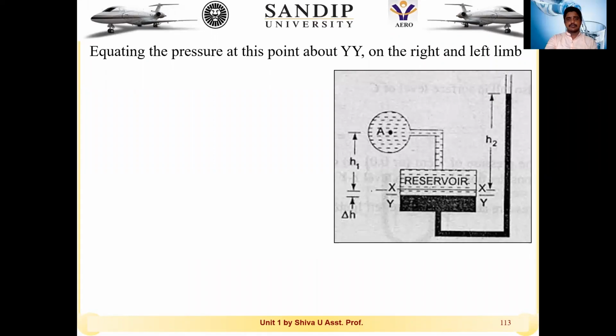As you can see in this image, the construction looks similar to the U-tube manometer, but on the right-hand side we have one limb which is extended like a tube, and the left-hand side is similar to the previous example, but we have one reservoir placed in between. The reservoir area is 100 times greater than the right limb area.